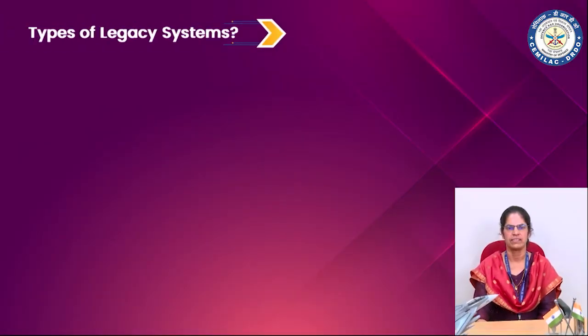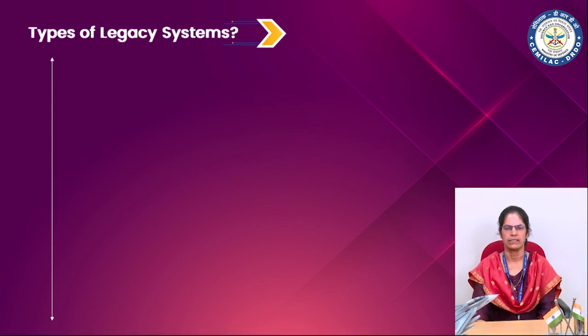Gracie, shall we quickly look at what are the types of legacy system software that is defined in DO-178C? Sudha, first of all, let us understand the legacy system software as per DO-178C. It arises when there is need to use software previously certified for earlier standards. FAA advisory circular gives us the guidance for transitioning to DO-178C while making modifications. There are 4 types of legacy systems.